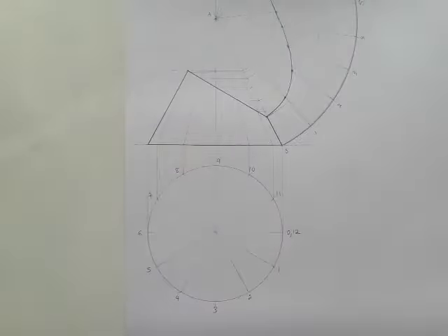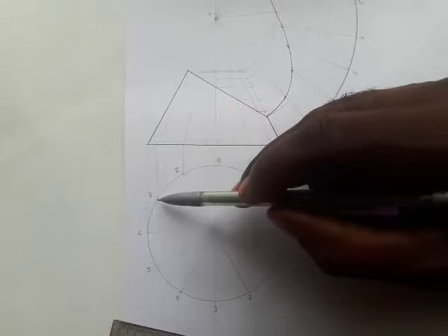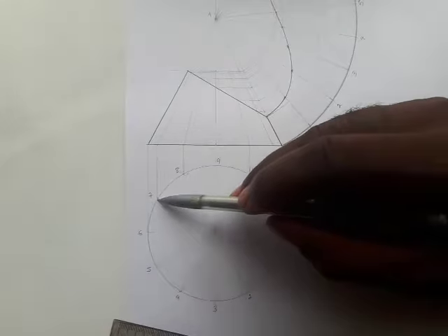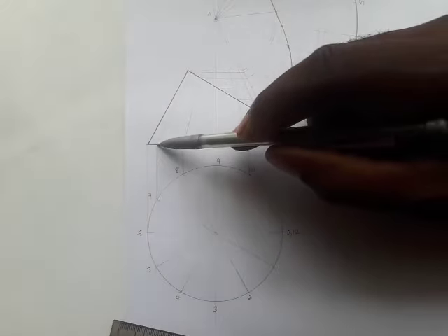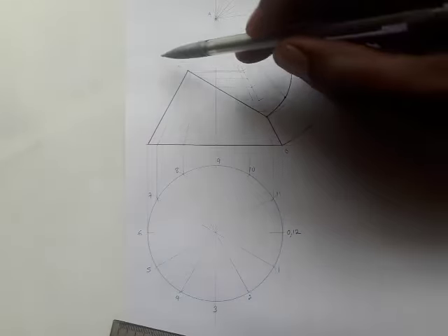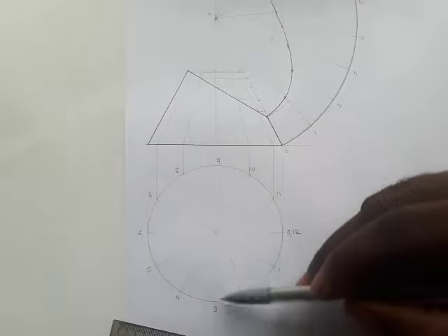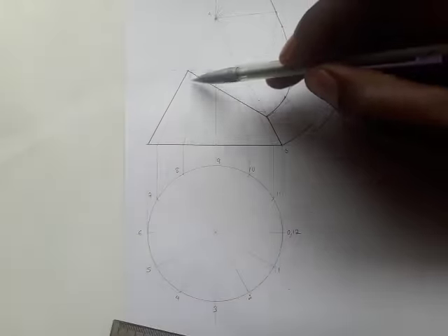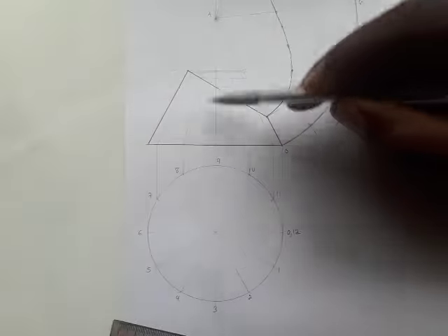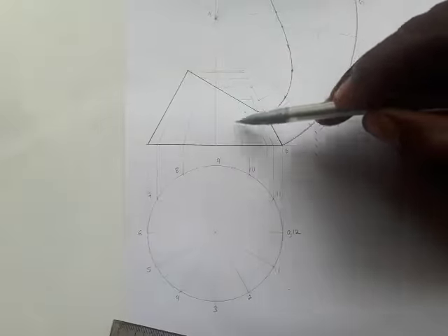Now what you do next is to draw lines from this point of intersection here. Now look very closely. You see this is line 5 and 7. Do not forget, when you trace, this is the point where it cuts the section surface. So you're going to transfer vertical lines, parallel to this center line, down from this point of intersection, all of them. Now 9 and 3 has already been drawn. Now you transfer lines down.